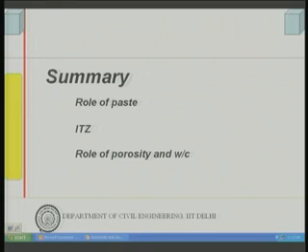total porosity and the pore sizes, and then when we come to concrete, the additional feature comes in at the interfacial transition zone. This interfacial transition zone is formed at the boundary of paste and aggregate. It has somewhat different properties than the bulk paste, and obviously it is different from the aggregate. In normal concretes, aggregate does not fail, all failures actually take place through this interface. This interface has additional porosity because of the wall effect, where the cement particles cannot pack together very well.